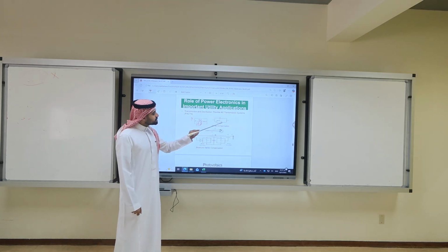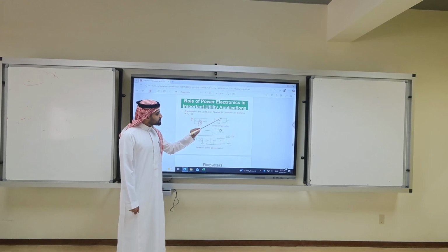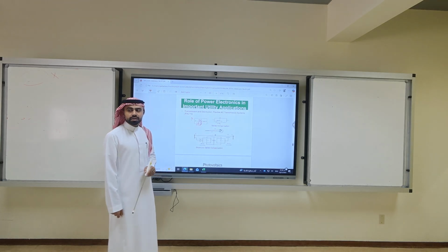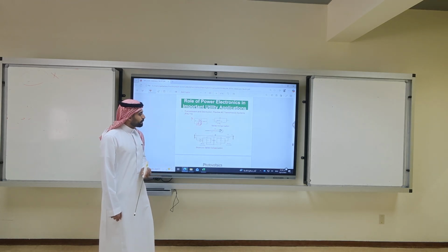So I add series either capacitor or inductor. These are thyristors. We add the series compensation to adjust the torque angle of the synchronous generator, so I can transfer more power.